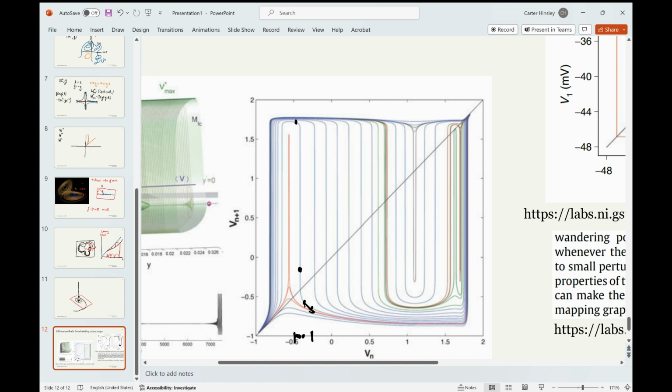And the dynamics are really, how do I say this? Expansive in the full system in places where this is happening. So you might be near a saddle fixed point or something like that. And so you're going to be highly susceptible to numerical inaccuracy. So you might not even be getting real trajectories because you might have floating point imprecision problems going on that are getting exacerbated by the dynamics. You might have a stiff system of differential equations or something like that. And the solver that you're using might not be good. Your tolerances might not be big enough, and so on.